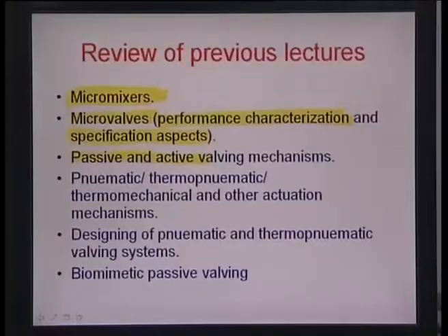We further categorized valving into passive and active valving mechanisms, and we discussed different kinds of actuation mechanisms like pneumatic, thermopneumatic, thermomechanical, electrical, magnetic and some other actuation mechanisms.